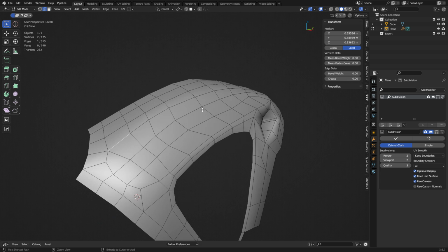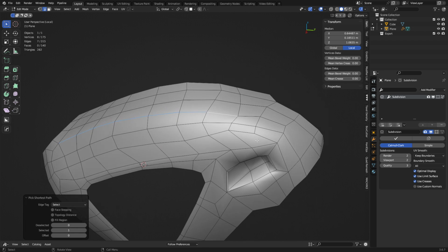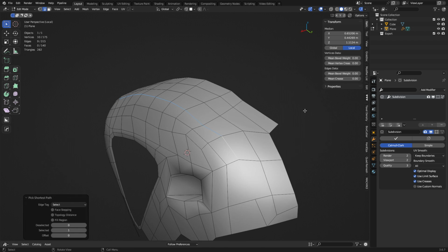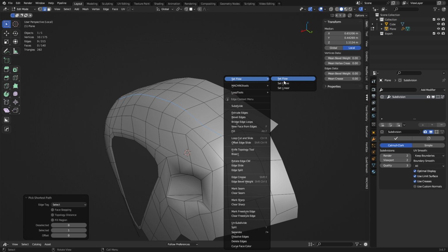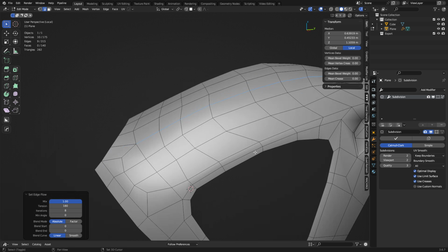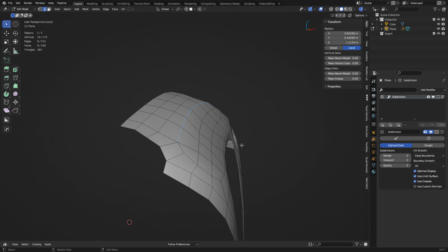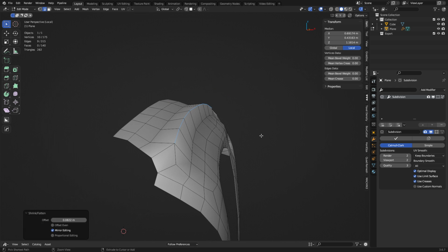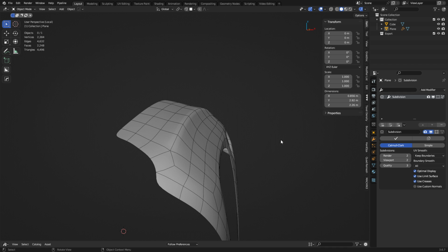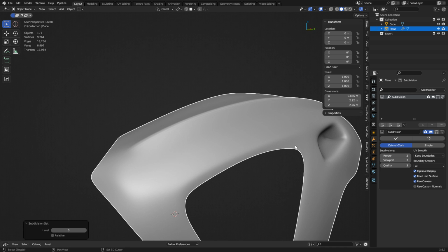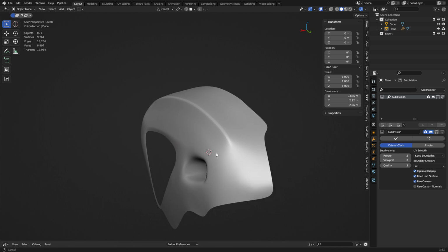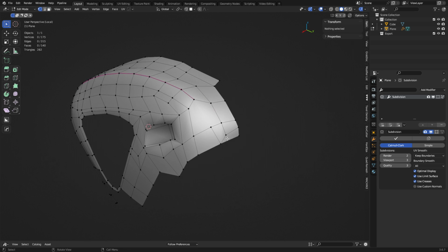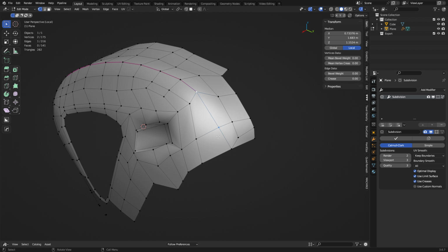And there's other little key things you can do as well, like adding creases still. Okay, or doing set flows, like you could use a set flow add-on. If you want something to remain a little bit more curvy, you can do things like that. You can Alt S them out, Control V, smooth vertices. Maybe we want a slight ridge here, so we can do a crease on this. Don't set it to 1, maybe like 0.8 or something. So when that subdivides, we get this really nice sharp piece like that. Right. We'll join these two back up.